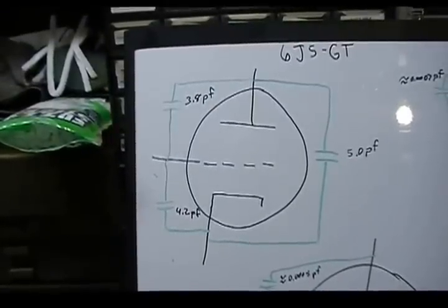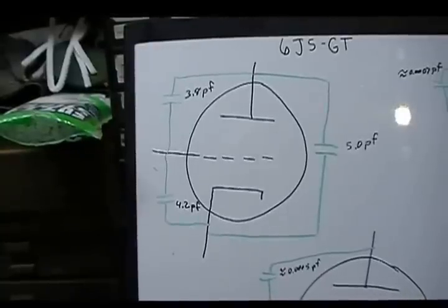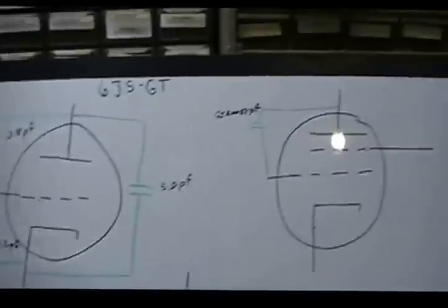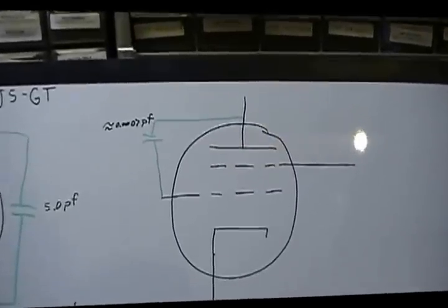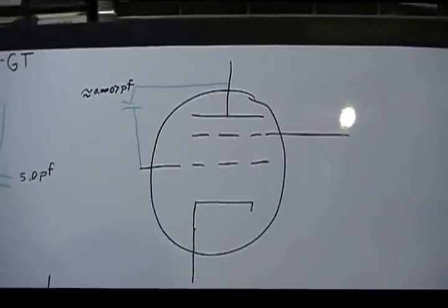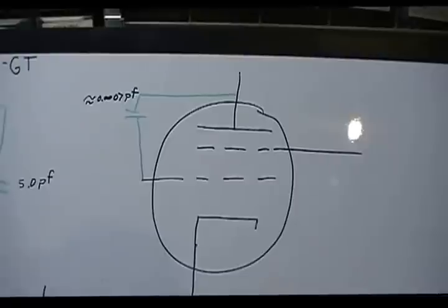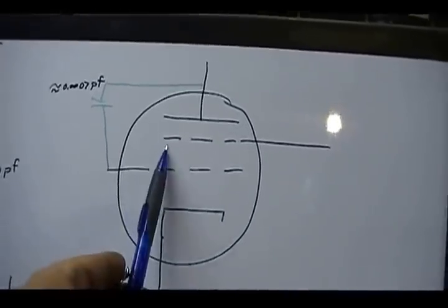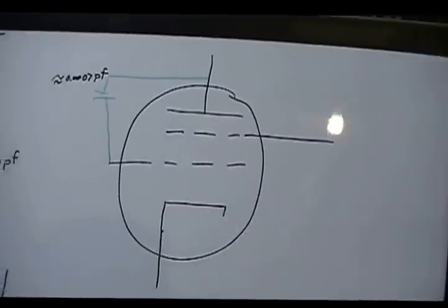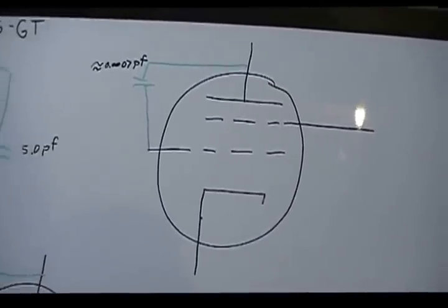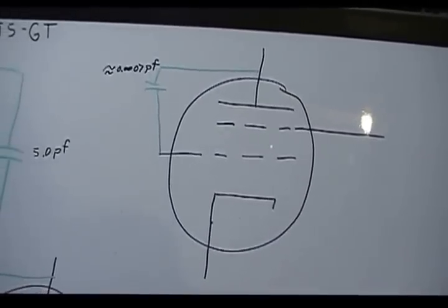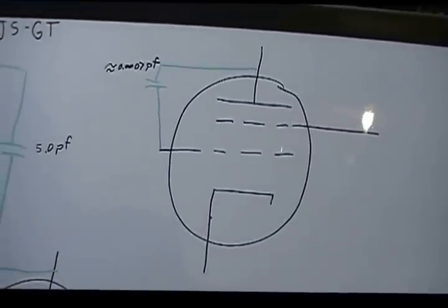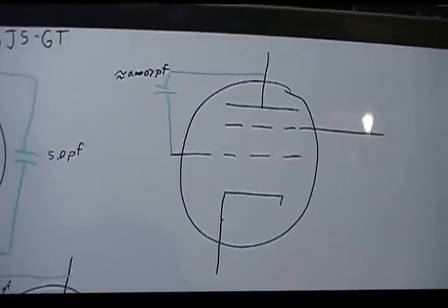So manufacturers of radios demanded something be done, so they left it up to tube manufacturers, and lo and behold, we have the Tetrode. It was born. Now, just like the Triode, except it has an extra grid, this one right here, called the screen grid, because it's basically screening the control grid, which is what this is, from the plate as far as capacitance is concerned.